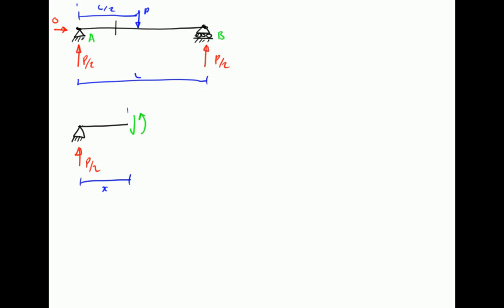Okay, so in terms of static equilibrium, our equations of static equilibrium for this free body, we know that we have a force of P divided by 2 acting upwards as a reaction, and that gives rise to internal forces which need to counterbalance what's going on there. So we have an internal shear force initially, and by the principle of sigma, the sum of all the forces in the y direction, if you remember, we chose for this particular problem y to be vertical, x to be horizontal, and z to be out of the page, or out of the screen.